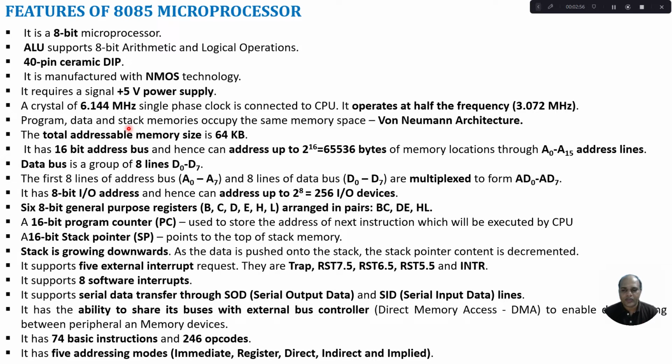Before moving on to the subroutine or to the interrupt service routine, the return address and also the associated registers for the main program need to be saved in some memory location. For that we can make use of this stack memory.